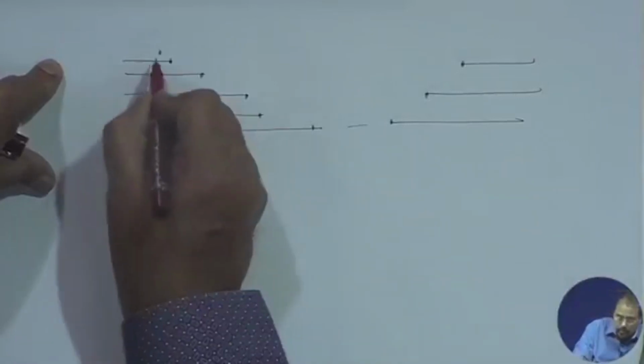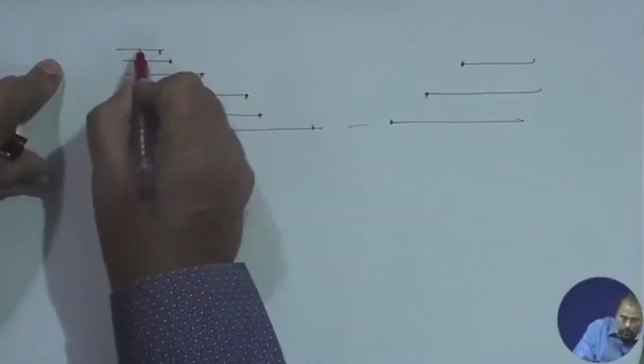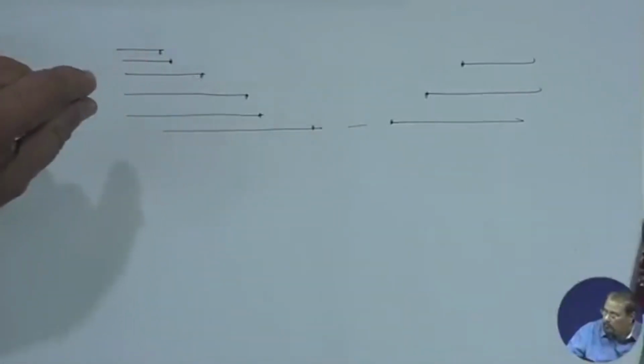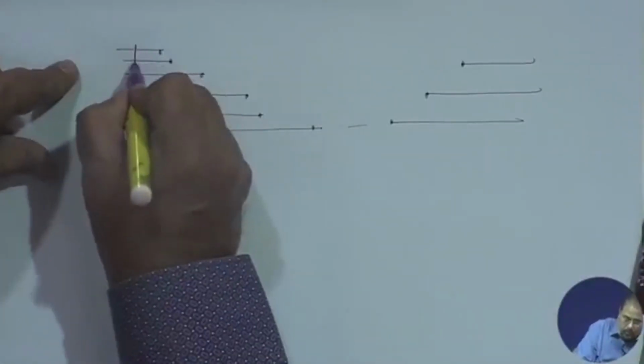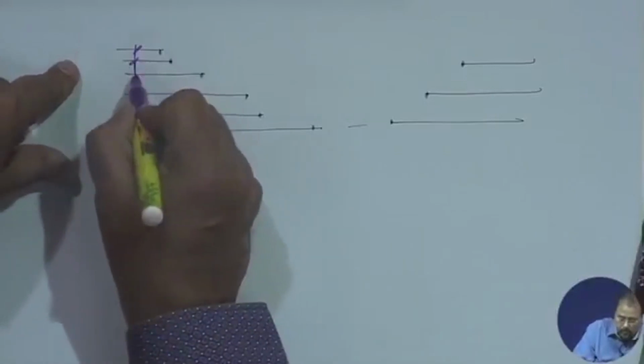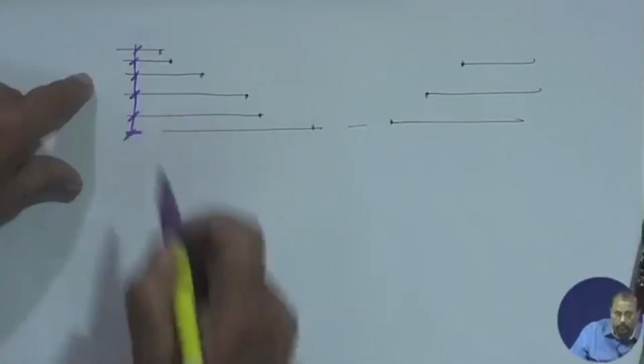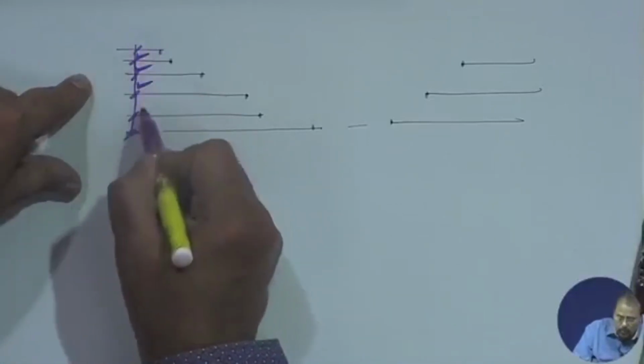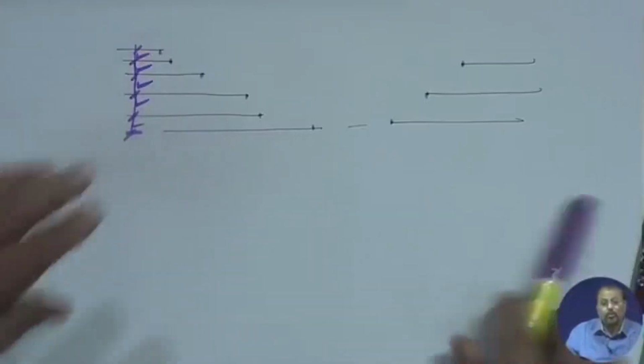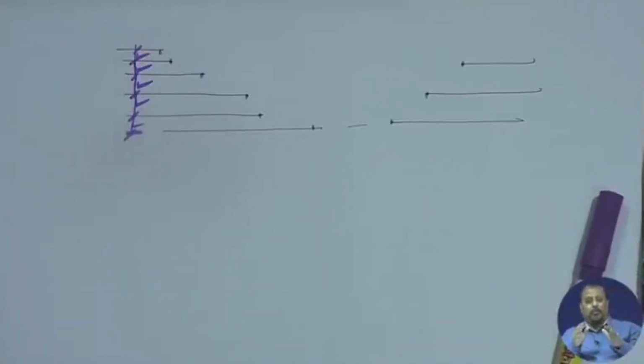Okay. The condition of this contour drawing is this is the dimension by which it is lowered from one to another. This is equal to this, to this, to this. That means contour lines in a contour drawing are at equidistant intervals vertically, but not necessarily is the position of that in plan at the same distances away.